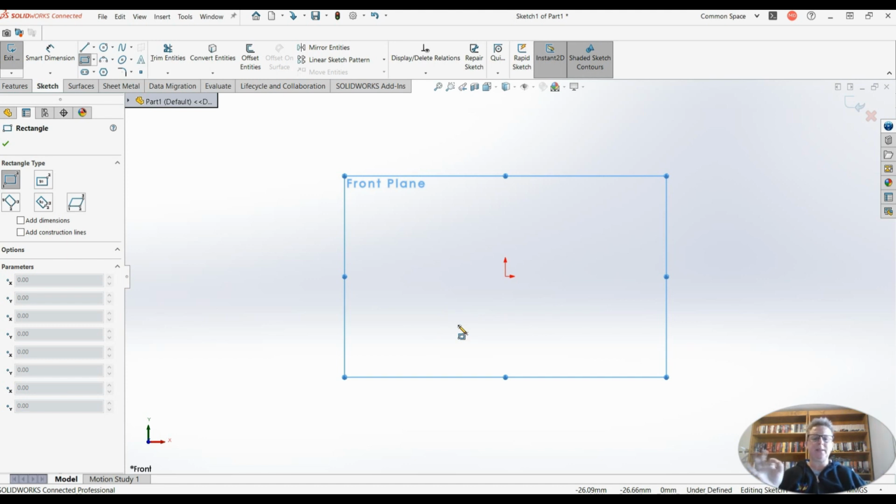And underneath that pencil is a corner rectangle symbol. So it kind of tells us that's what we're going to be drawing with. Now, hopefully you'll see I've got these reference lines here. They're just reference lines to tell me that I'm directly in line and I'm not clicking anything. They're directly in line with the origin. If I bring my pencil tip right to the origin, you see, there is a little orange dot. So we want to start at the origin.